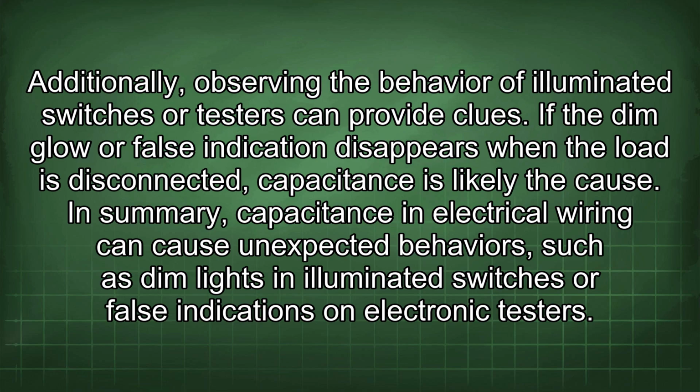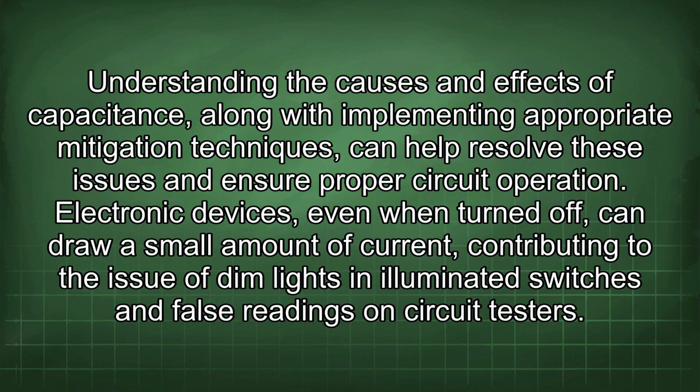In summary, capacitance in electrical wiring can cause unexpected behaviors such as dim lights in illuminated switches or false indications on electronic testers. Understanding the causes and effects of capacitance, along with implementing appropriate mitigation techniques, can help resolve these issues and ensure proper circuit operation.